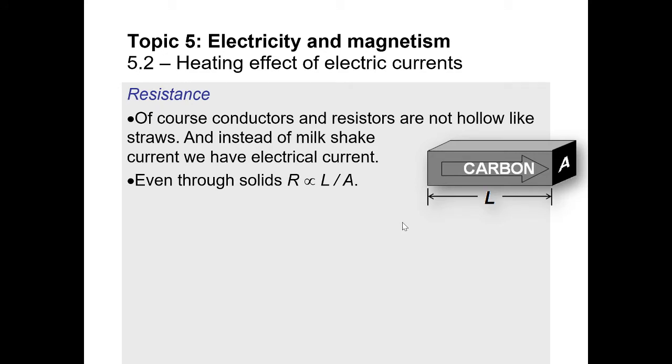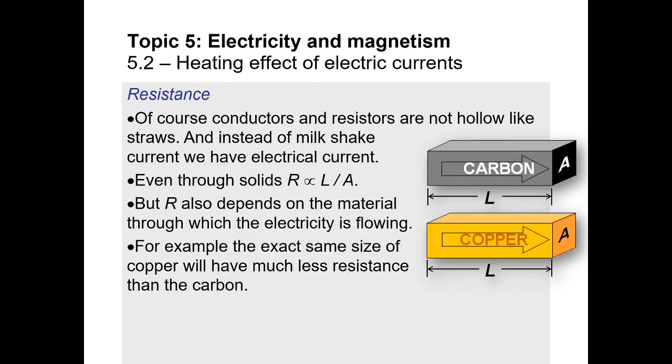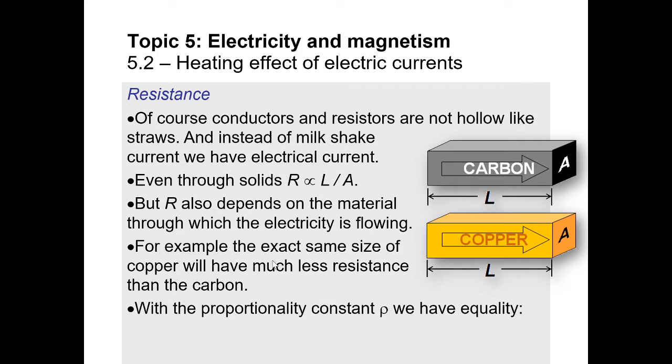Trying to figure out that constant comes down to understanding why we use different materials in electrical work. After all, we saw that carbon does conduct electricity, but we don't use carbon quite a lot, especially not in wires. Wires are usually made of copper. Why copper, and why not another material? Well, it all has to do with not just its resistance, but that constant of proportionality, which we're going to call the resistivity. That word is going to be on the next slide, but in the meantime, you have the symbol here. This is the Greek letter rho, and I will write that down on this sheet.